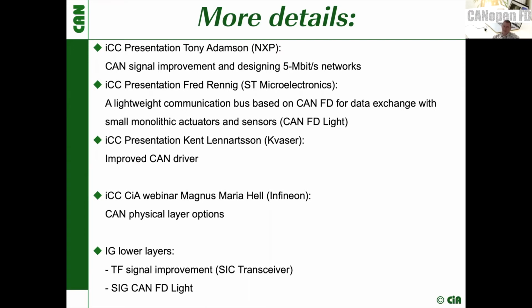In a similar direction goes the presentation from Kent Leonardson, who talked about improved CAN drivers. He was playing around with the slew rate, and this matters more if you are avoiding the bit rate switch, because when you're bit rate switching, I think the slew rate is more or less fixed. But when you have a flexible slew rate and you run lower bit rates, which you can also do with CAN-FD, then you can play around with the slew rate and calm down the ringing and avoid putting in too much voltage.